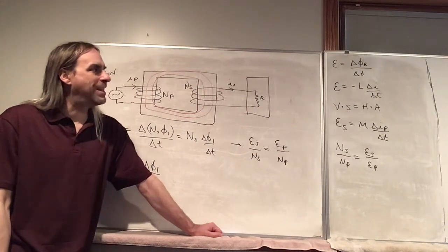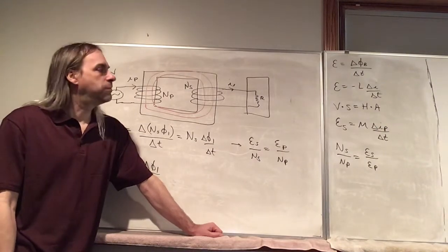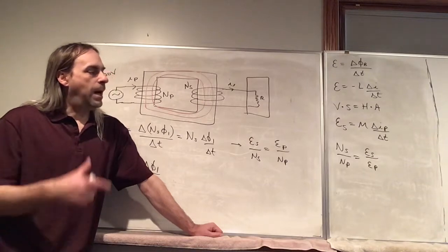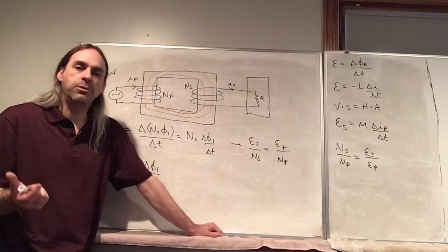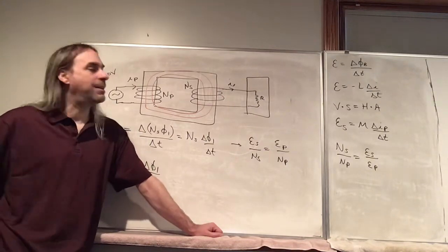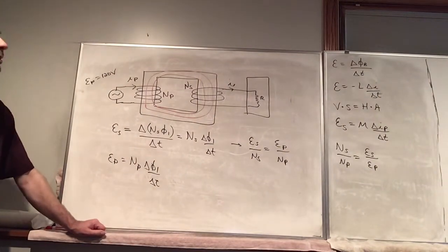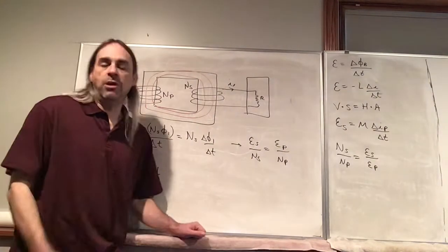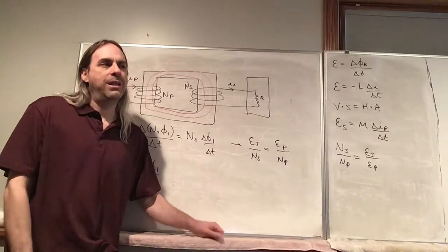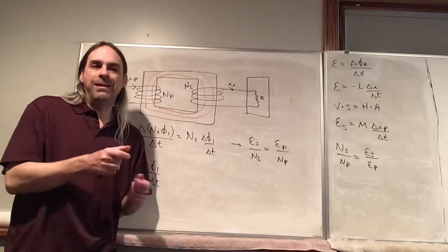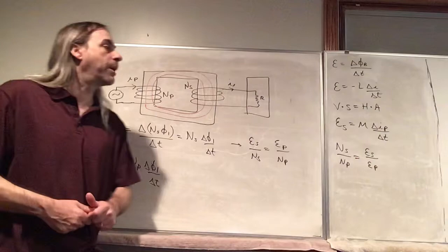Now, our power grid is actually a bit more complicated than that, because we have different lines going to your house that are all about 120 volts, but they're all offset from each other. We described how they're described by a sine function, but we have different lines that are offset by 120 degrees. The reason is you can combine them in different ways to get, say, 120 volts or 240.